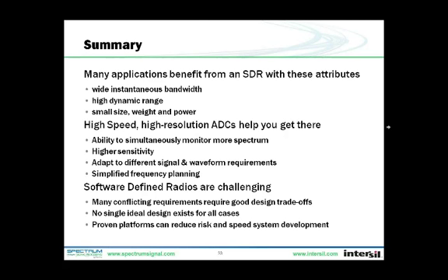They also have the ability to simultaneously monitor more spectrum. They give you a higher sensitivity, and they can help you adapt to different signal and waveform requirements. They also simplify frequency planning, since signals, harmonics, and their aliases can be separated more easily as they appear further apart in the output spectrum. We've reviewed a real-world SDR platform that uses a high-speed ADC and some of the considerations involved in implementing that.